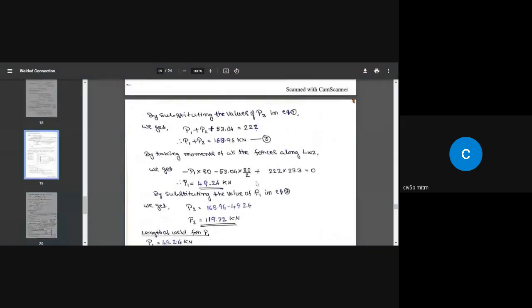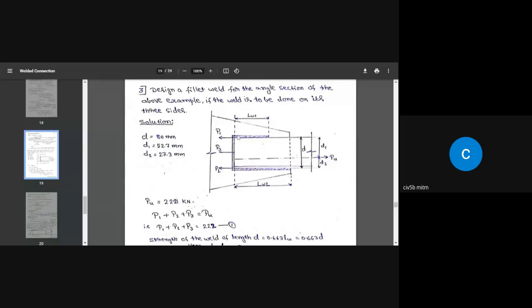Minimum effective length of the weld is 74.27. So what is the actual size of the weld we need? 74.27 plus 2 times the weld size, 86.27. Of course, we are not going to provide 86.27. Instead, we are going to go ahead and provide 90 millimeter length weld of size 6 millimeter. Is it clear to you? That means we are providing 90 millimeter length. Okay. Next.